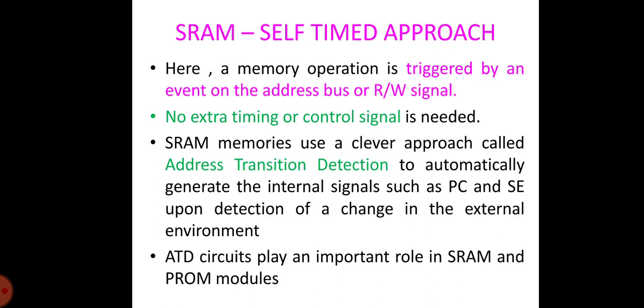The fact that this drop is only that much, despite the cell area reduction over the same period of time, is solely due to various cell innovations. At the same time, the increased integration density raises the noise level due to coupling. While the problem of word line to bit line coupling capacitance was already an issue in the early 1980s, closer line spacing has brought the bit line to bit line coupling into the limelight.